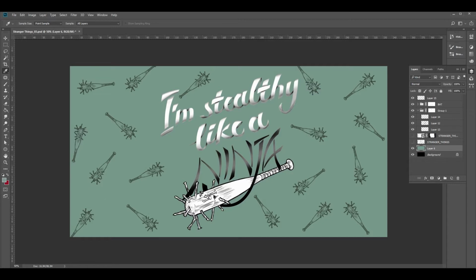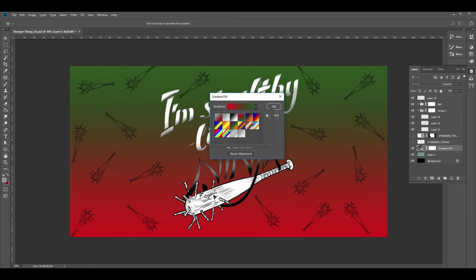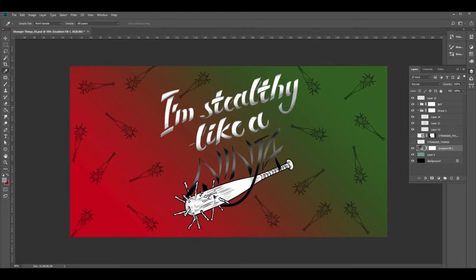I thought you can make it directly on a new layer by using Gradient tool. Instead, I'll show you another feature offered by Photoshop called Gradient Fill. You can find it in the same menu where Levels layer is. Different options appear in the windows that pops up. There are a series of predetermined gradients you can choose from, or establish one of your own. You can also establish the angle you want it to have and gradient style. I've chosen 45 degrees of inclination for this gradient. It provides sensation of dynamism and makes lettering vivid.